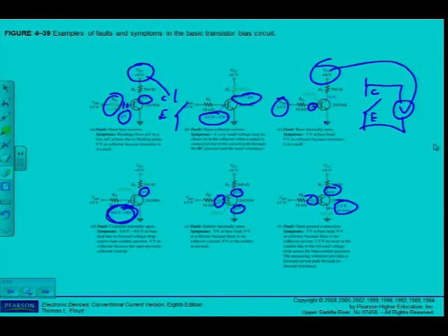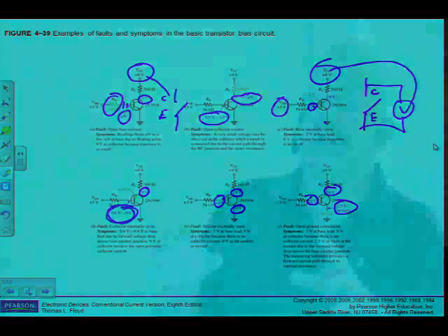But the important thing is that you have to calculate the values as expected for your specific circuit. If the circuit is not working, then at least you know what you have to measure at certain points in your circuit due to current flows, etc., and from that you can deduct then what the fault may be.